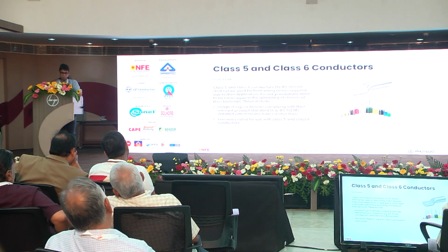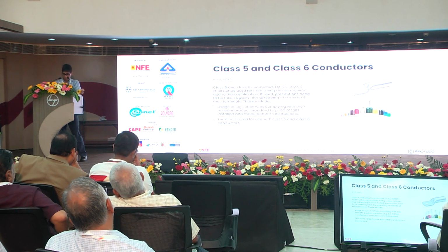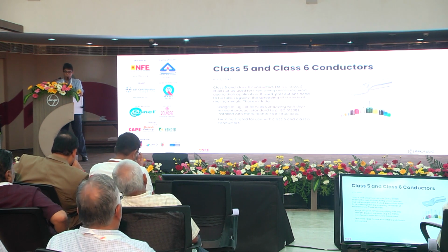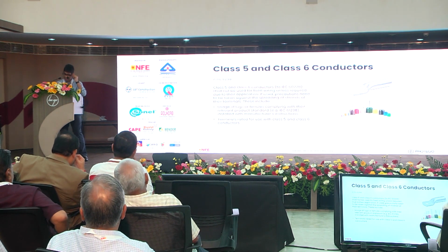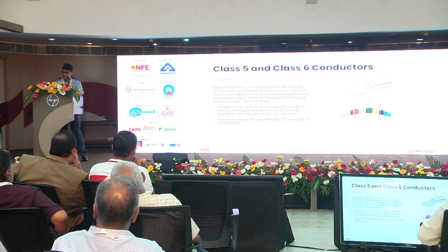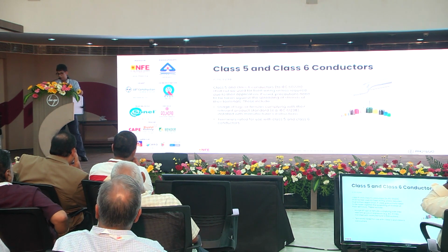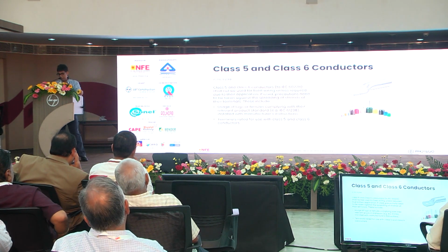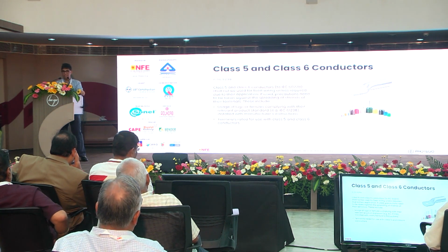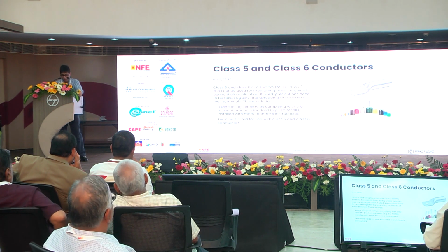If it is an MCB, a light switch or a socket, you need to use ferrules. Unfortunately, no IS or IEC standard exists for these ferrules. There are DIN standards, DIN 46228, for these ferrules. You can get these in the market very easily. I believe even Dowell's, which is a Polycab brand, makes these ferrules.